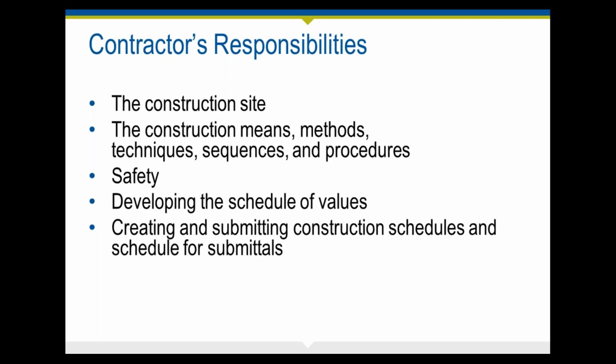That also means that they have a responsibility even before construction starts to visit the site, check the plans, and inform themselves of the requirements of the work, because ultimately what the contractor is responsible for are the construction means, methods, techniques, sequences, and procedures, and we'll talk about that. But this is an important distinction that has to be clarified as you understand what your role is in the construction contract administration place. This is a phrase that is well known in the industry, that means and methods, generally speaking, are the responsibility of the contractor.